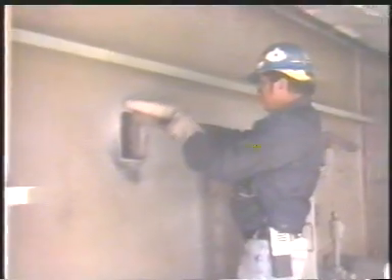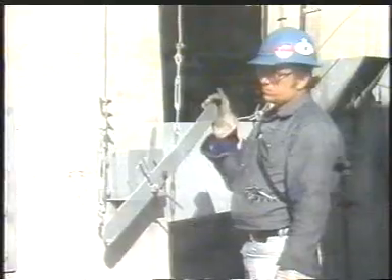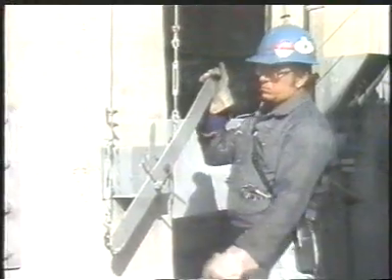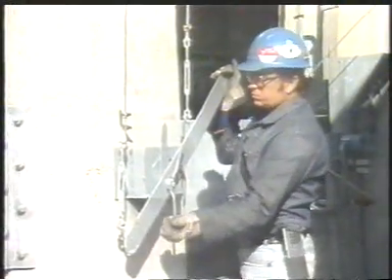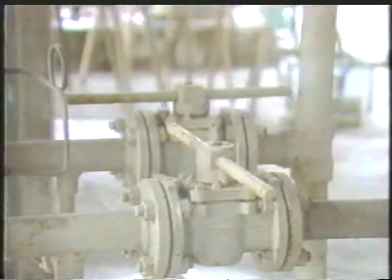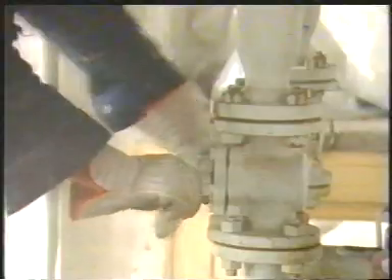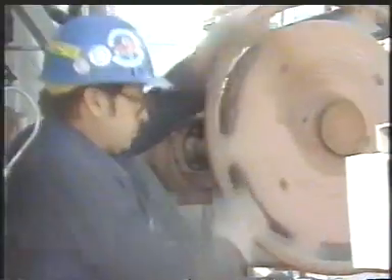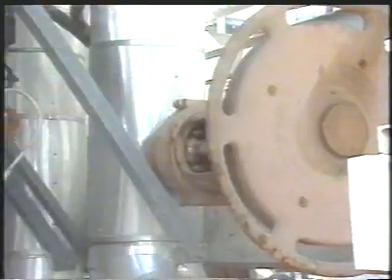When minimum firing has been reached, you shut off fires and open the PEEP doors. Process circulation is continued to cool down the tube slowly. Next, you open the stack damper and air registers to purge the furnace. Then block the fuel systems, including the burner and regulator valves. And when the furnace is cool enough, stop the process flow and block the process systems.